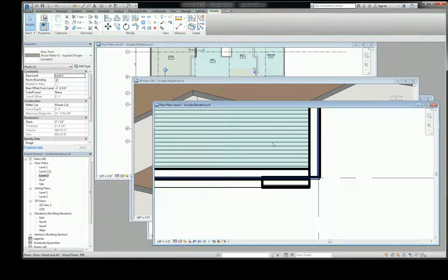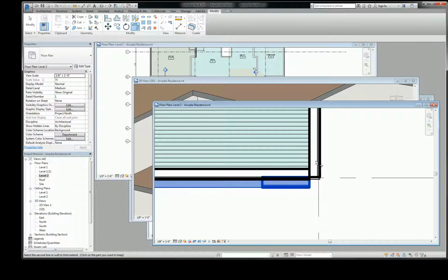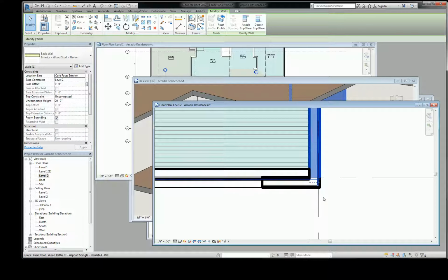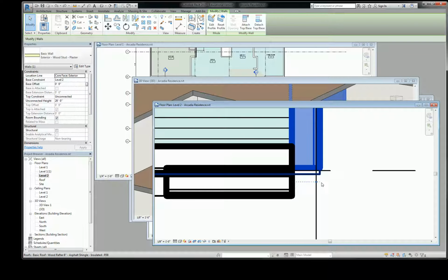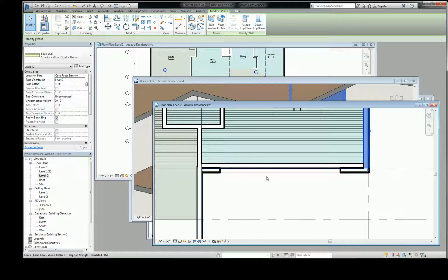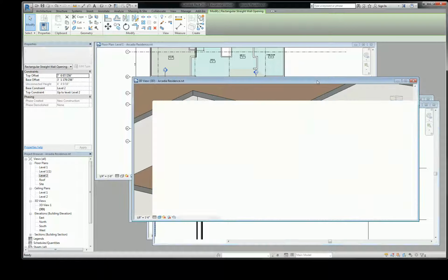So unfortunately, these corners, you're going to find that one of the most frustrating things for you guys as new Revit users is that these corners get really silly and they keep breaking on you when you're doing weird things. So I'll walk through troubleshooting this stuff with you over time, but if you just drag the little grip on the wall toward the corner you're trying to rectify, oftentimes it just fixes it for you. So anyway, I've got my opening in the wall, and I'm ready.